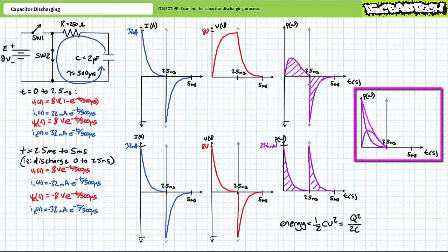If you want to think of it this way, during the charge phase, the source works real hard and supplies not only energy to the resistor, but also supplies a little extra to the capacitor. During the discharge phase, the source then gets to kick back and drink a mint julep out of a frosty copper mug on a shady porch while the capacitor does all the work. Regardless, the resistor experiences regular bursts of positive power, each burst delivering 64 microjoules of energy each cycle, regardless of which direction current is traveling.